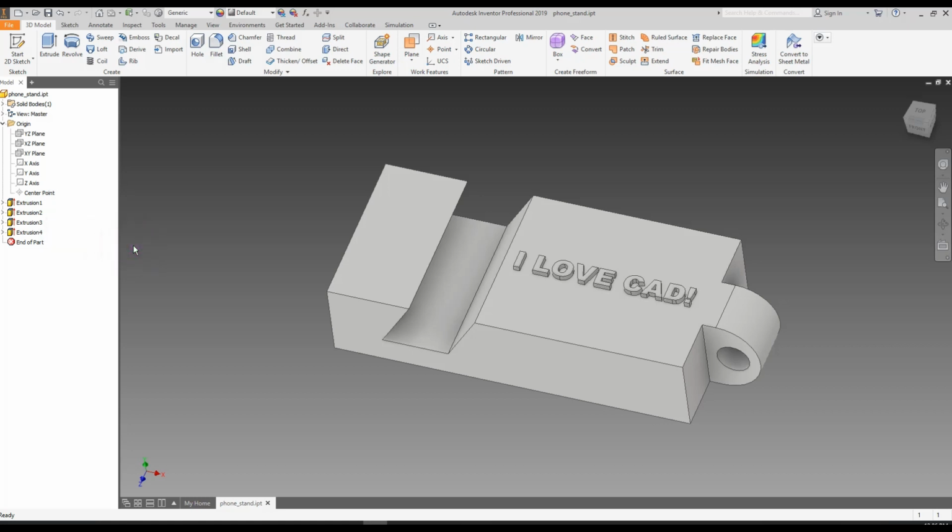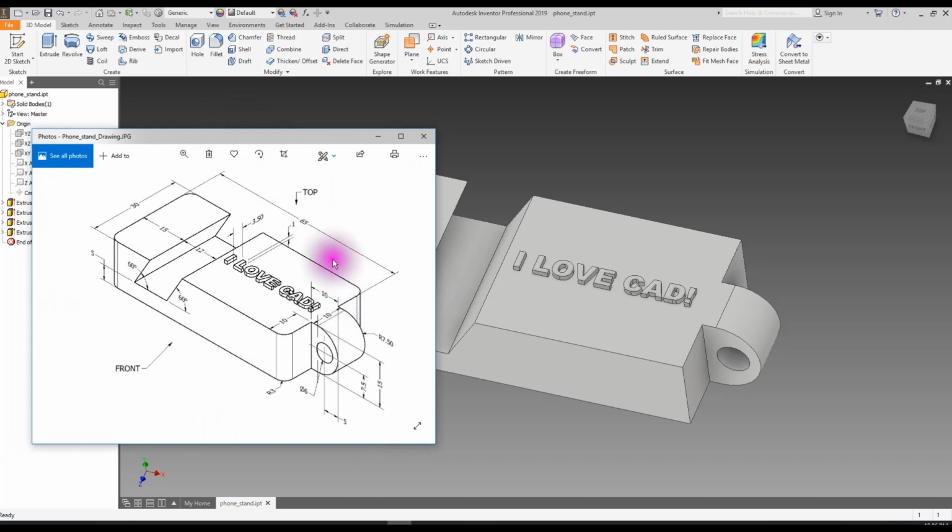So you're getting close to finishing your phone stand, but there's one distinct feature that's still missing, and that is these rounded corners. You can do rounded corners in several ways. When we did this first round, we made it as part of the sketch because it was just easy to do it that way. But when you want to do rounded corners like these, it's easier to just add them on at the end, and we are making these corners by using what's called the fillet tool.